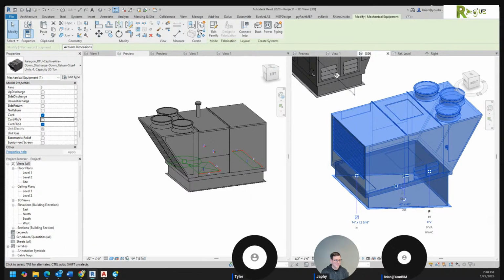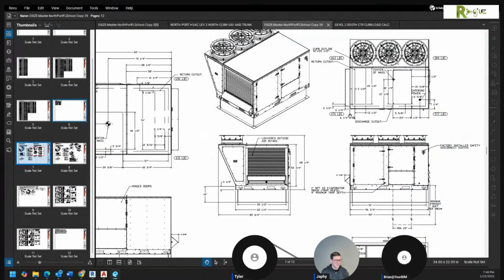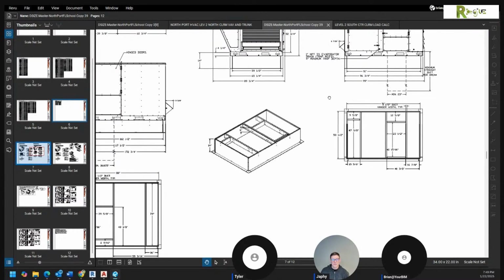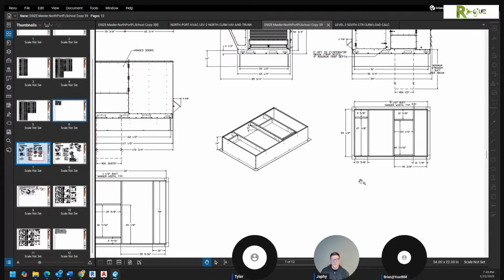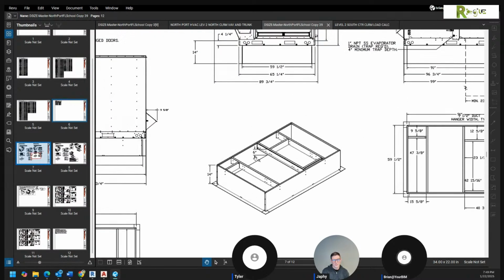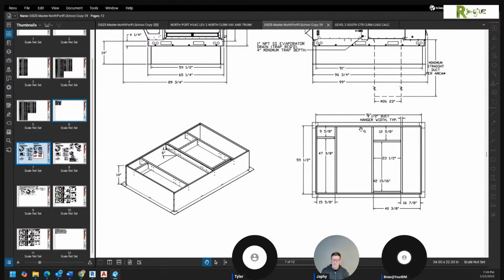So now look, here's where it all becomes a little bit obvious what I'm trying to do. You know those structural families I showed you, those channels and those things. What happens is they build these curbs. And I don't know if Eric's here or not. He was saying that things didn't look out of scale. If this is 14, this isn't 6. Well, that's not what this is trying to tell you. This is trying to tell you this is using 2x6 light gauge framing. And there's what the framing is supposed to be.